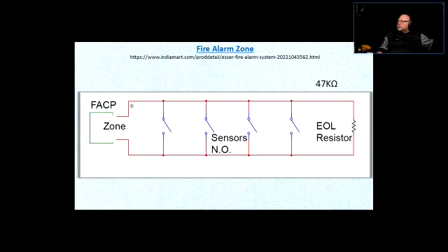When the situation is at rest, the fire alarm zone looks at the end of line resistor, and if it sees the value of the resistance that it's looking for, then it considers that zone to be at rest. So everything is okay. Now, what happens if the cable is broken? Somebody does some work and by accident they rip the cable apart. Then the zone would see no resistor at the end of the line, and it would trigger into something called a trouble condition.